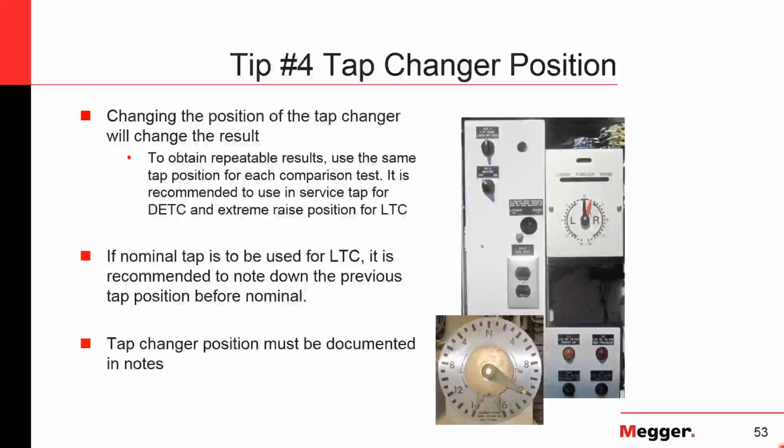So looking at this, there's a couple things to consider. Everything's overlapping a little in here, so we don't have specific established ranges for core, for winding, and everything. But typically, on your open circuit test, when you're looking at the low frequency ranges, that is your typical core result. So you'll see maybe a core connection that came undone, or you might see that the core's magnetized and different things like that.